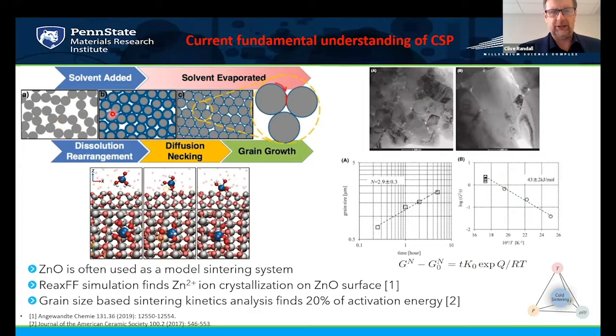This is zinc oxide. You then rapidly heat the material, say 15 degrees a minute. You then have, on the surface, very, very small amounts of liquid phase, less than 5%. And then it drives a dissolution process. And because the system is open, it's different from the hydrothermal process. So you exploit non-equilibrium thermodynamics. And that will then take a solute into that surface liquid.